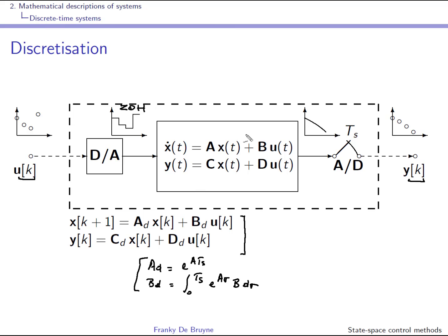So we have a way of going from the continuous time state space description to the discrete time difference equation, right? And if we use this representation in the design of our discrete time state space controllers and observers, we take the zero order hold into account in our design, and as we will see in the course of digital control, that's a very good thing.